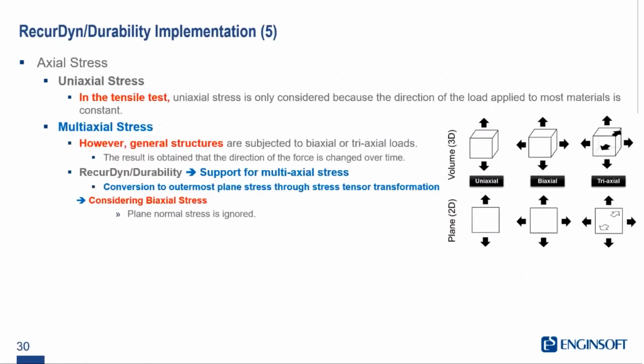Moving on, it's worth talking about the difference between uniaxial and multiaxial stress, and this plays into some of those correlation models as well. Again, the idealized form is a uniaxial loading condition. I like to think about this as those material test samples where we're just applying a load up and down to see when it breaks. That's very clearly a uniaxial problem. Rarely does that happen in the real world, so more often than not, we have multiple axes that need to be considered.